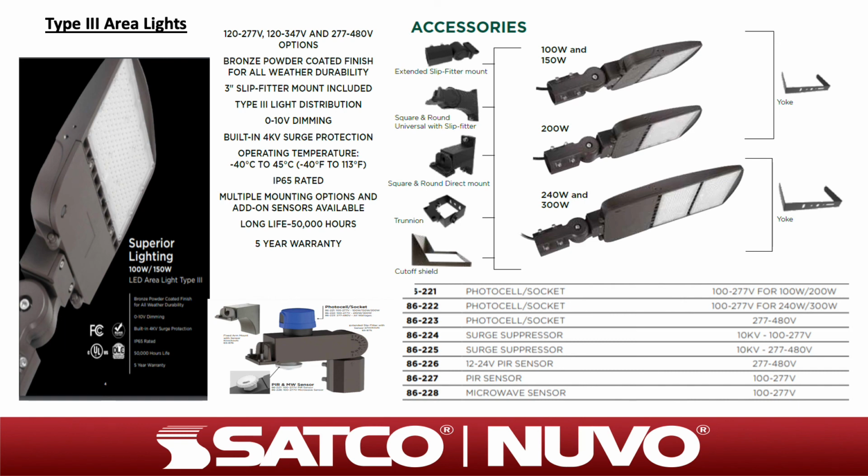The area light family offers wattages of 100, 150, 200, and 240 watts. Mounting options include yoke, trunnion, slip fitter, and universal mounting. Control options are photocell, passive infrared, adjustable microwave sensor, and 0 to 10 control. Additional accessories are light shields for light trespass concerns and 12 kilovolt surge suppressors.